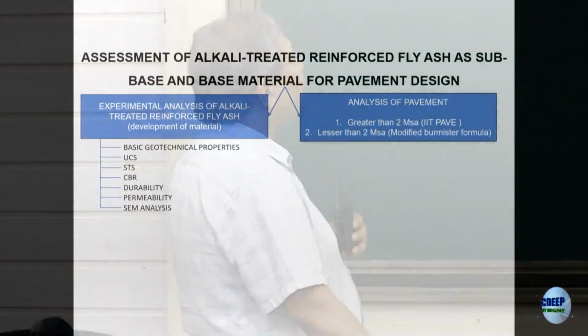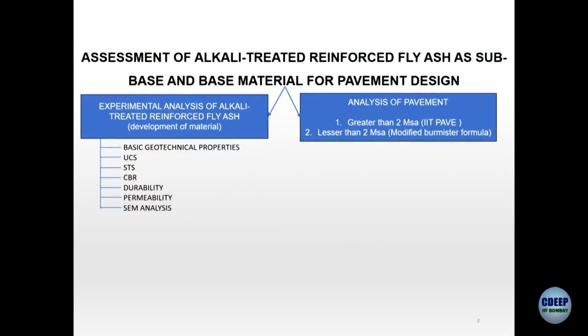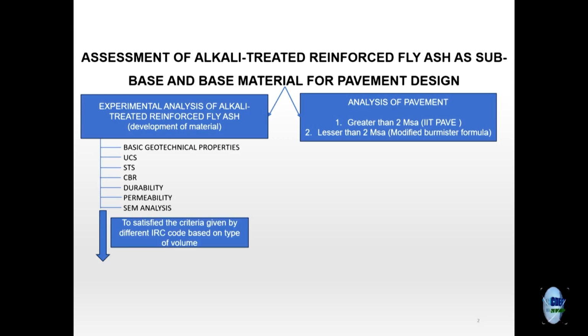This is the whole logic. With time the gel gets solidified and crystallized in form. So these are the basic tests, the UCS, STS, CBR, durability test, permeability and sieve analysis, that I have done. It is based on the various types of IRC codes that have been given to us.